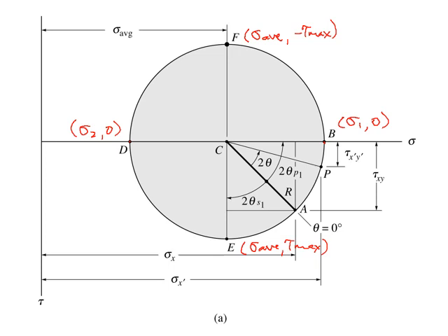Now someone might ask me, sigma 2 shouldn't it be negative? Yes, it could be negative if it goes to the left of the shear stress axis because that's 0, right? Now if your circle goes to the left, sigma 2, the value is 0, but normally we just write it as sigma 2. Similarly for sigma 1.